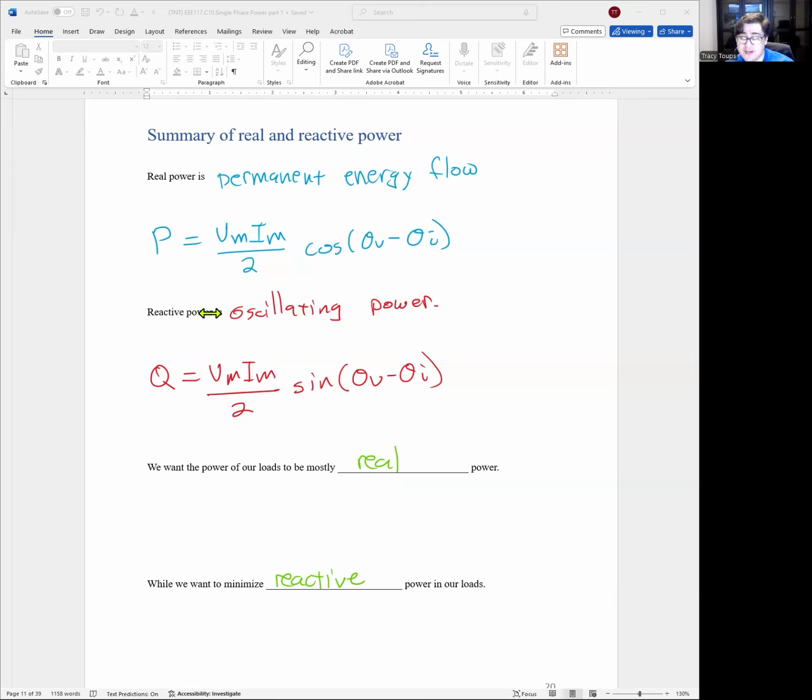So, from here on out, especially in the power industry, your managers are going to talk about real power P and reactive power Q. The instantaneous power, v of t equals all that cosine trick stuff, you're not going to see that anymore, not too often. Mainly these two are the driving power equations for all of power engineering. I breathe, eat, and sleep this stuff at work all the time. We're talking about P and Q for power calculations, so just get used to seeing this.